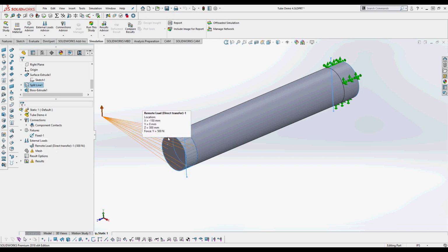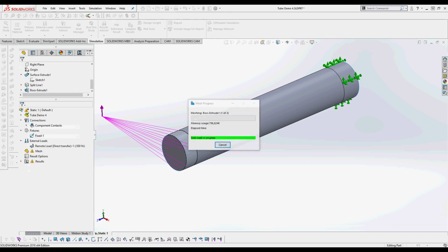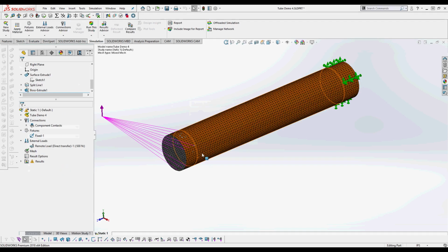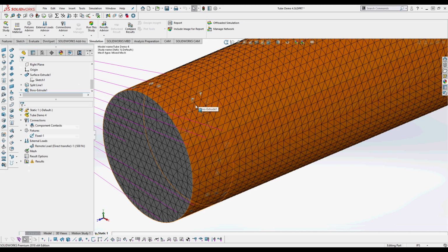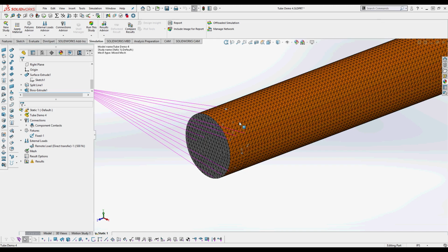Okay, so now we've changed the geometry, so that necessarily means we need to recreate the mesh. We can probably use the same settings. Now you'll note that where we have these two overlapping bodies, we have this overlapping mesh. We've got a surface mesh and a solid mesh. They overlap, and the nodes are coincident. So these meshes are what we call compatible meshes. So the simulation will directly interface loads and deformations at each point in the overlapping mesh.